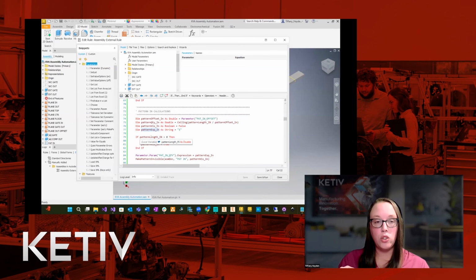That is going to be crucial in issues where you have a calculation problem and for some reason your calculation for the pattern is, let's say, less than 1. You don't want the pattern to error. So you want to reset it to 1 and then continue on. And when you know that it's less than 0 or less than 1, you'll reset it to 1 and turn the visibility off on the pattern.